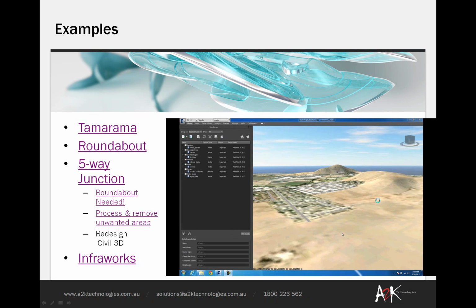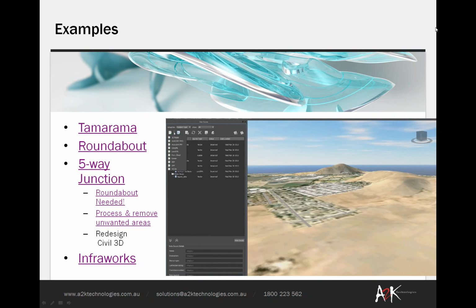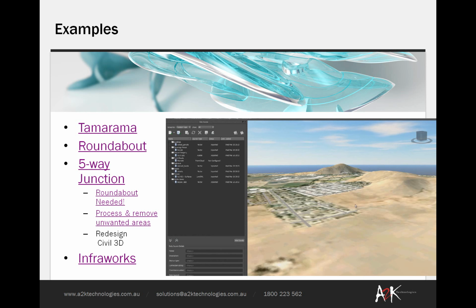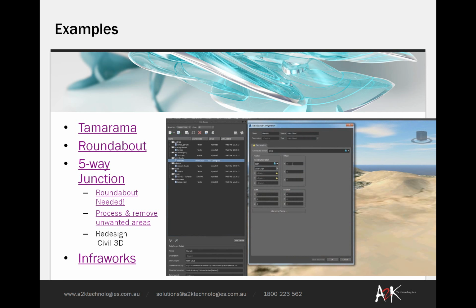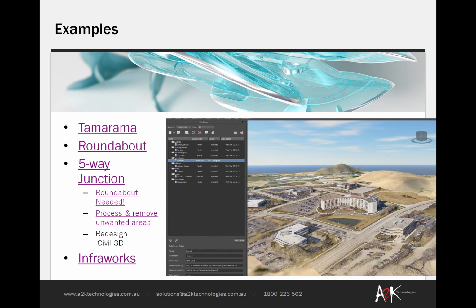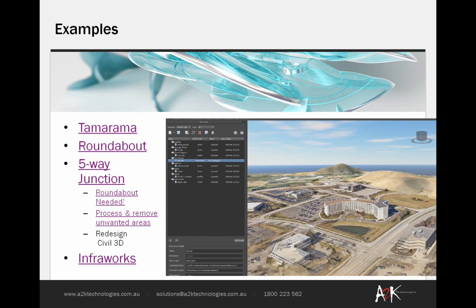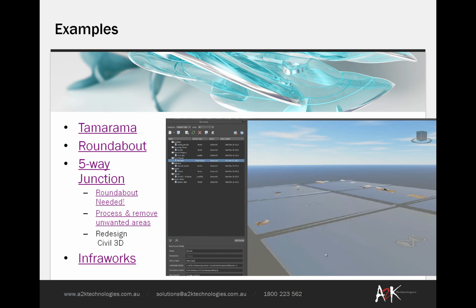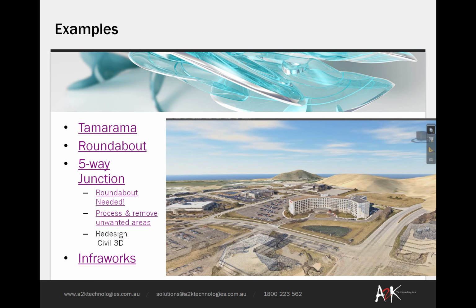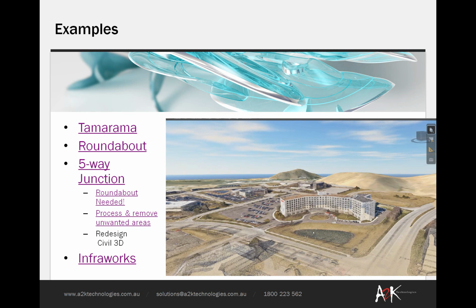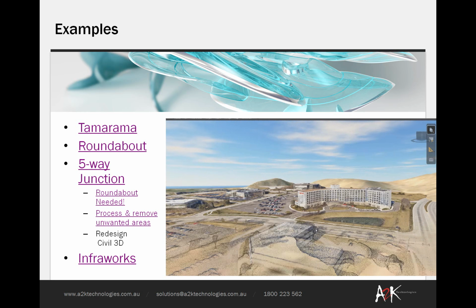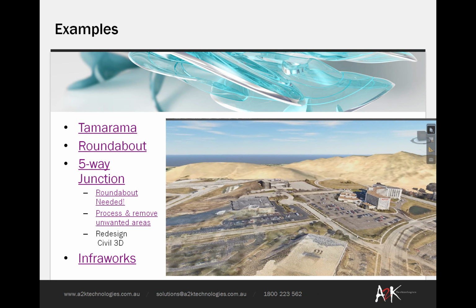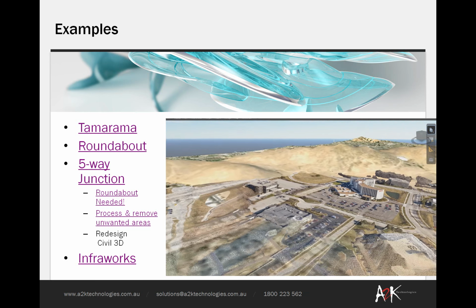So the last thing we've got here is a large survey coming into InfoWorks. In this case, it's one of the examples auditors have given us, and what you're doing is you've built up an InfoWorks model with the aerial photography and terrain models, and you can now deposit a huge point cloud into that. Once that's come in, you can start designing new features based off your geometry. So this adds a huge level of reality to your design process. And again, it's just done by photographs, which is the part which still fascinates us. So you could take this and pick your areas of interest, design them, and show exactly how they will look in the real world.